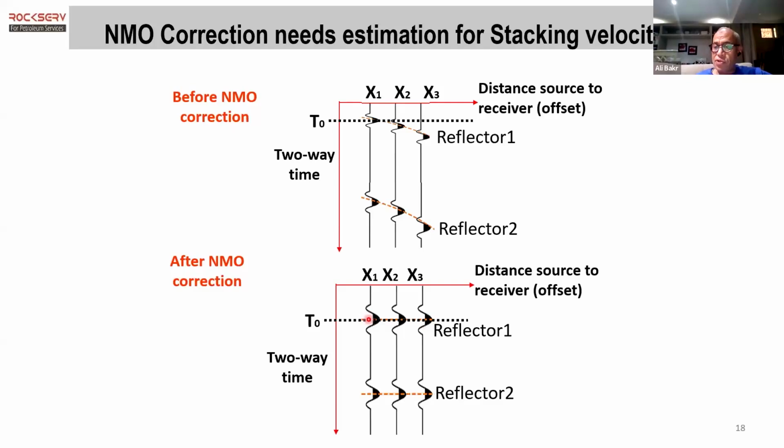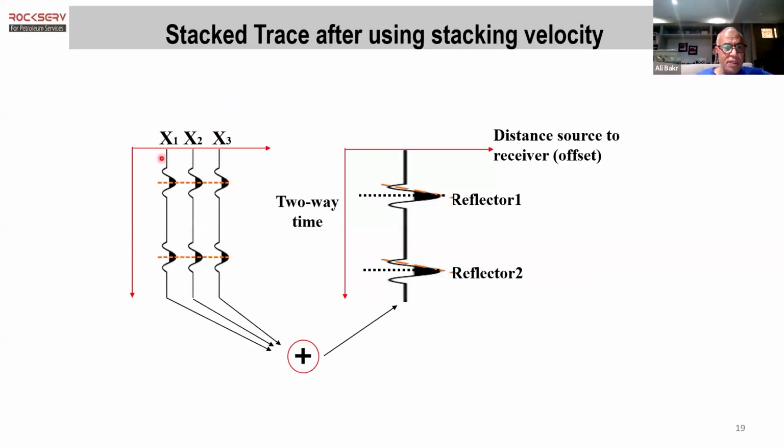And for us, it is almost the vertical reflection. Actually, it's not typically vertical, but we consider the first shot-to-receiver at a small distance, with some correction, to be vertical. And then after that, we can continue with the other corrections. Okay, now this is exactly what happened. X1, X2, X3, we have a reflector, and then the second reflector, and this represents a reflection point, and this represents a reflection point, but still assuming that the two reflectors are horizontal.